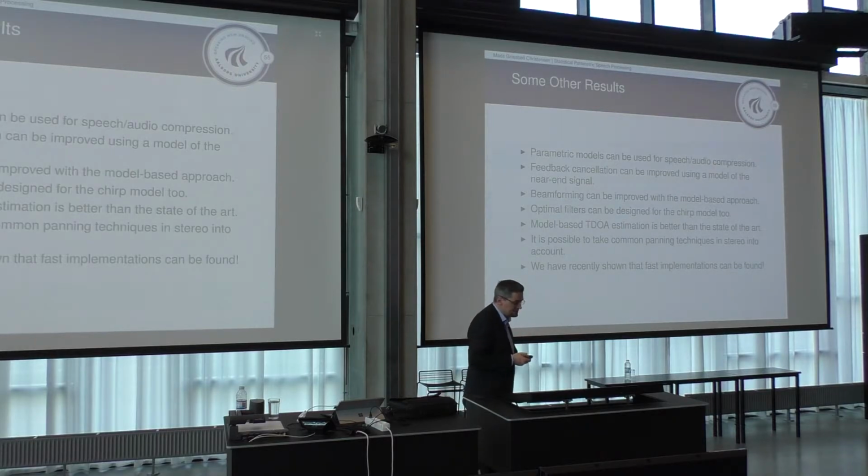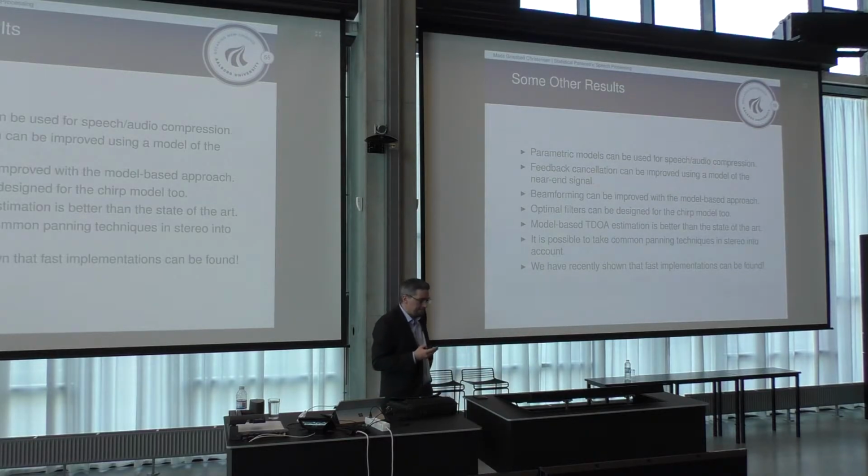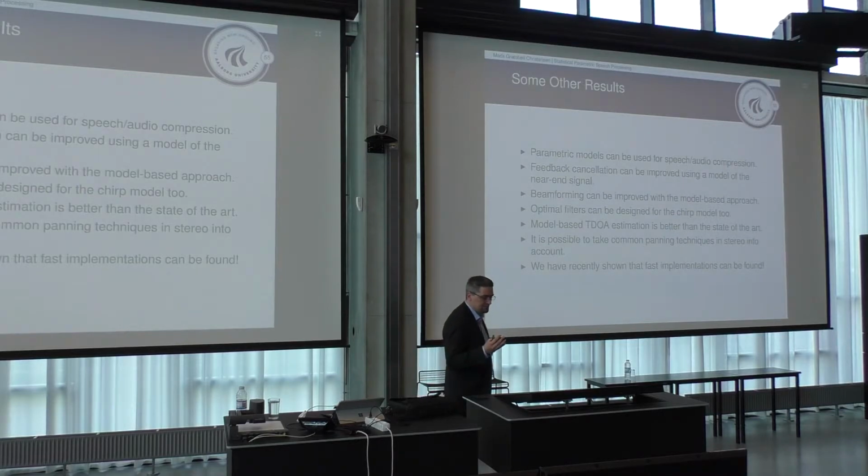Some other results that I'd like to briefly mention here. We've also shown that parametric models can be used for speech and audio compression. We've shown how these models can be used to improve what is known as feedback cancellation. So feedback cancellation is used in basically any communication system, where you probably encountered it with cell phones and Skype and all that. You get echoes from the far end, and you use feedback cancellation to avoid that. And if you use these models, you can do this better than with traditional methods. You can do better beamforming when you have microphone arrays with the model-based approach.